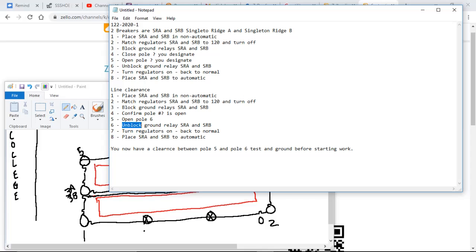Have you ever been doing switching along these lines and somebody comes back in, they're on a pole between where you're at and they're trying to close something or do something, and you have to wait? You see the step procedures here, this is relatively short, 8 steps. When you get a switching order, I've seen switching orders up to 900 steps. You can't go out of step order. If that answers your question.